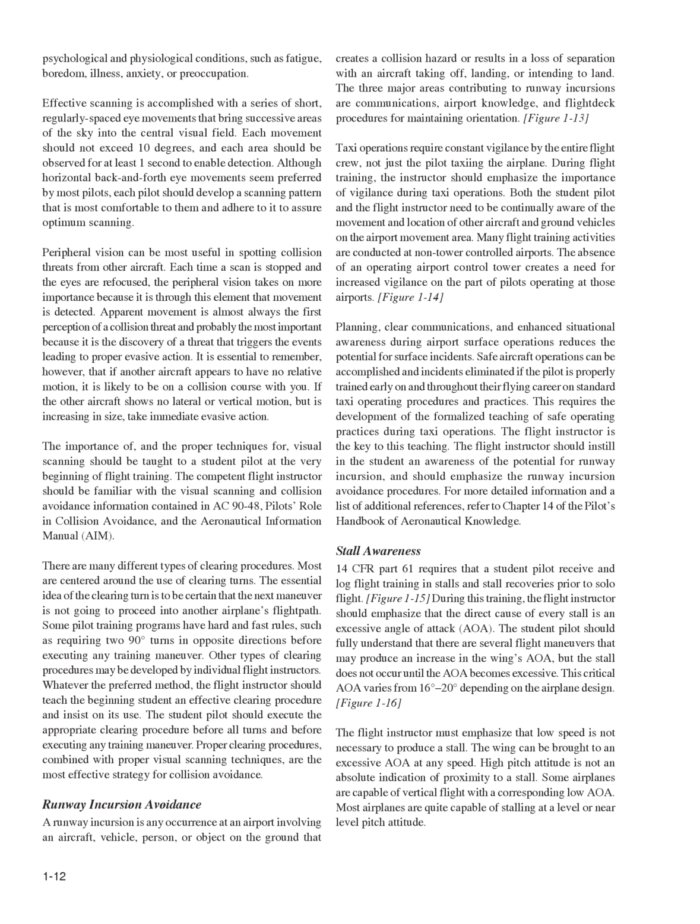Runway incursion avoidance. A runway incursion is any occurrence at an airport involving an aircraft, vehicle, person, or object on the ground that creates a collision hazard or results in a loss of separation with an aircraft taking off, landing, or intending to land. The three major areas contributing to runway incursions are communications, airport knowledge, and flight deck procedures for maintaining orientation.